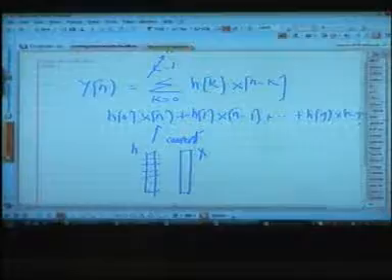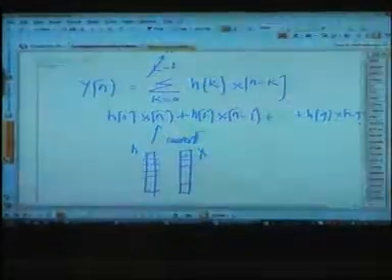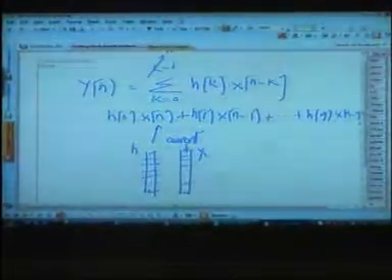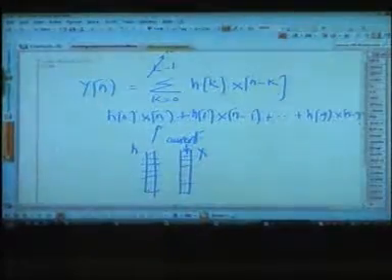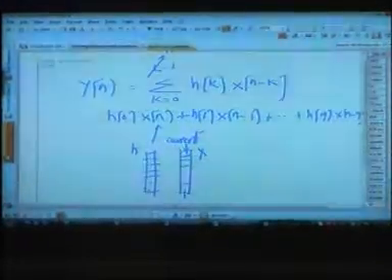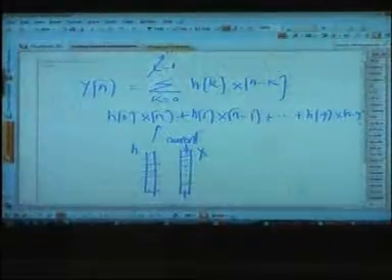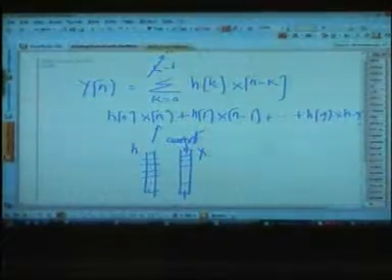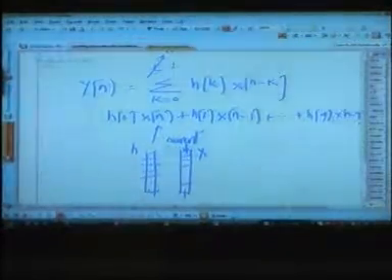X also has 10 values, but this is a dynamic array which is changing all the time. Every time you add a new sample, it gets into this location of your X buffer, and the old value gets out of this buffer. We also call this a tap delay line. So continuously you get data, and you need to maintain this array X. H is a constant.